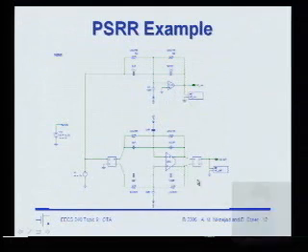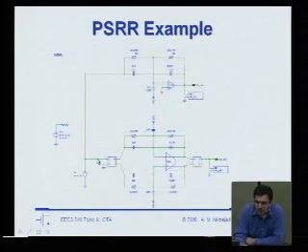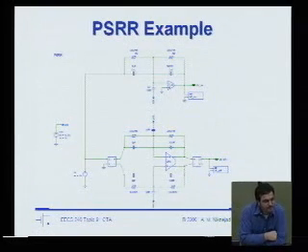So here is a fully differential amplifier, and this is the balun basically on the input. This is the balun on the output, and you can see here I want to have 0 input common mode, so I just ground this terminal, and then from this terminal I drive it with my input voltage. And here a fully differential signal will develop with a common mode of 0. And then on the output I can measure the common mode signal by just tapping this node and looking at what voltage I see. And I can take a single-ended load now and put it here, and I know that automatically the right differential load will be presented to my amplifier. Okay. Questions about that?